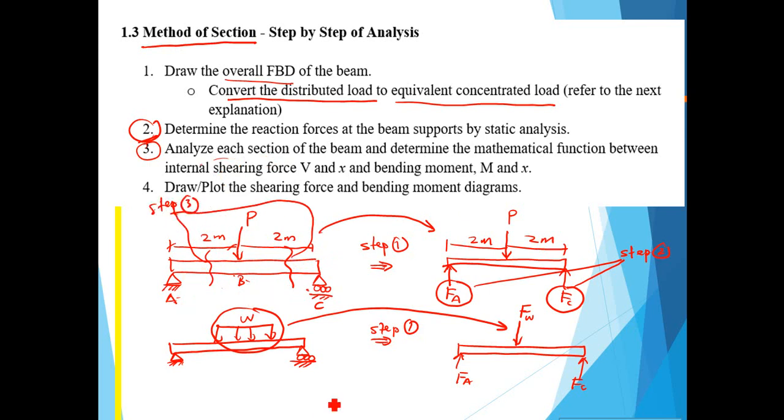And then step 4, draw the shear force and bending moment diagram. We draw the shear force diagram, which is V versus X, and the bending moment diagram, which is M versus X. So step 1, draw the free body diagram, and if you have distributed load, convert it into concentrated load.